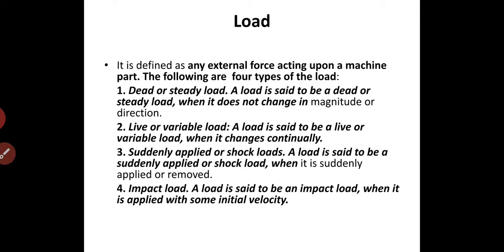Load. Load is defined as an external force acting upon a machine part. Following are the four types of load from the subject point of view: dead or steady load, live or variable load, suddenly applied or shock load, and impact load. Dead or steady load: a load is said to be dead or steady if it does not change in its magnitude or direction or both with time.